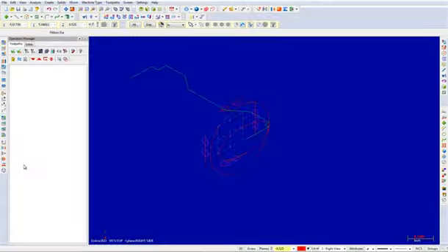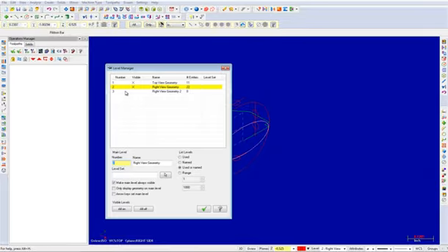From here, click on Clear Colors to return the geometry to its original color. Your part will appear as shown. Now we will create the circles on the left face. Choose levels from the status bar and make level number 3 active. Click on the X in the visible column beside level 2 to make only level 1 and 3 visible as shown. Now select the OK button to exit the level manager.